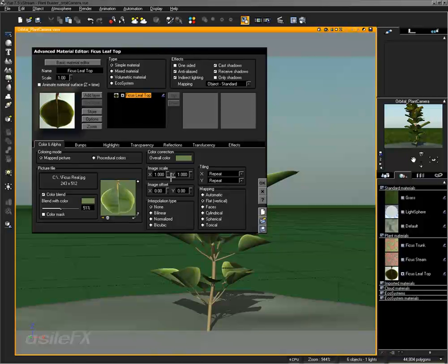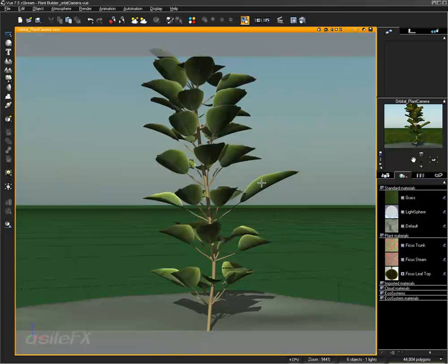the scale. Now the scale of leaves, in order to get them to show up properly, and even though it's an object standard mode, it really works more like parametric, where it fits to the shape and size of the leaf polygon. And it's actually set up at 0.34. So your scale for your leaves needs to be 0.34, which was the scale of the mixed material. But since the materials within the mixed material were set to 1, when I removed the mix, it removed the mix scale.